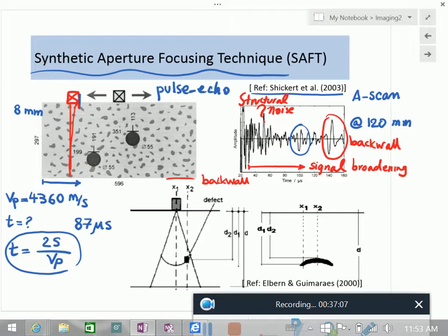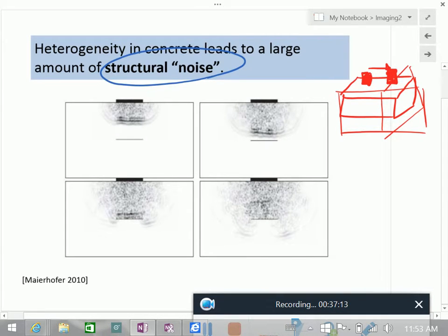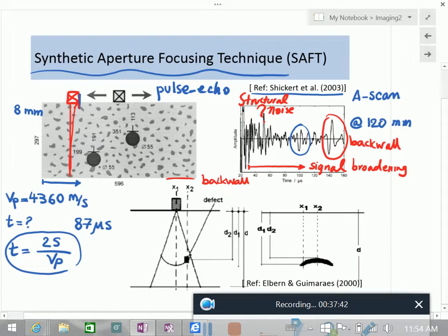Okay, let's go back to the previous slide again. This is the wave field for a transducer. Do we have wave field only underneath the transducer? No. It's stronger just underneath, but we also have it elsewhere. So it is like a cone shape. The transducer is very strong when you look down, but then it still has some strength, and then it fades. And this is the phenomenon that you see here. Even before you get here, you start seeing the object.